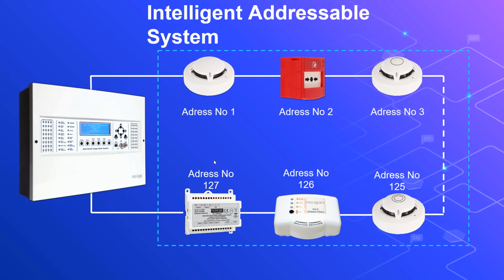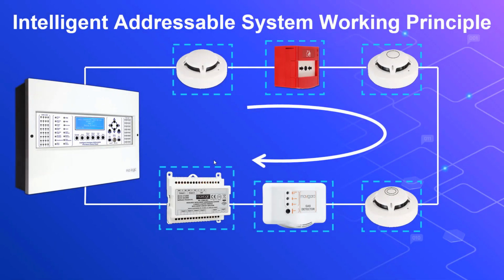In addressable systems, devices are connected to the addressable control panel's loop. The loop exists, the addressable fire alarm panel and addressable devices are connected along the loop, finally returning to the panel. All addressable devices connected to the loop receive separate addresses either mechanically or through software. Devices connected to the loop in addressable systems are queried at regular intervals. Faults and fire situations that occur in the system are reported to the fire alarm panel with pinpoint accuracy.